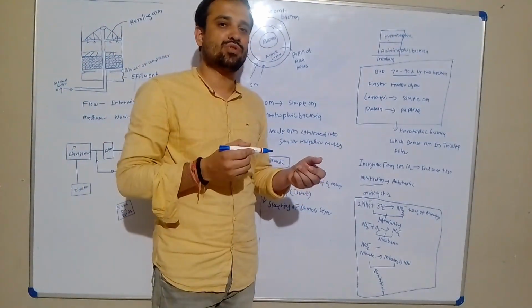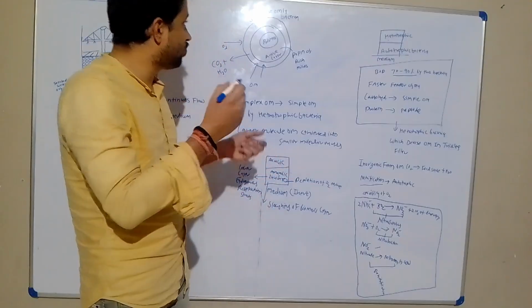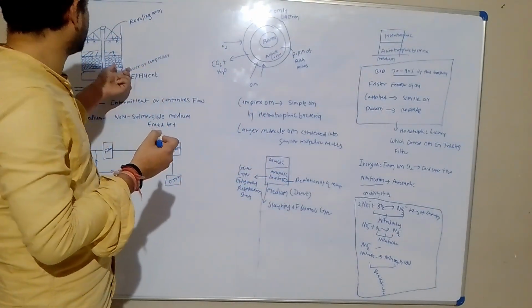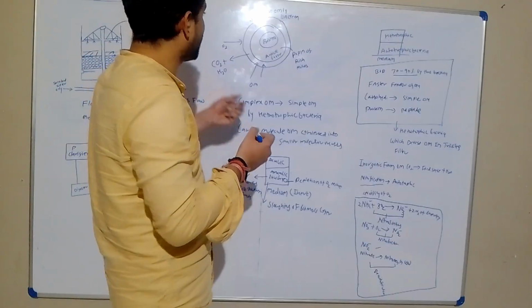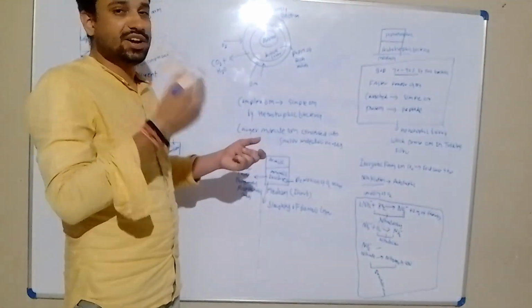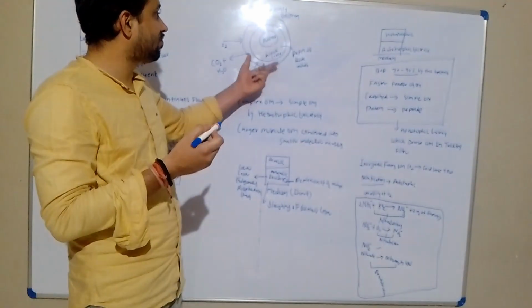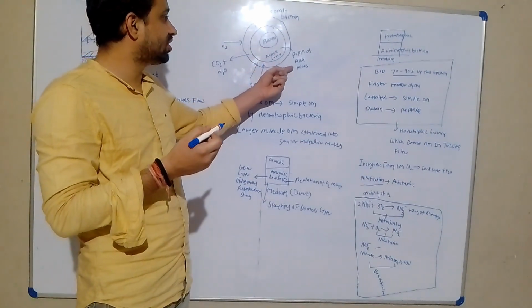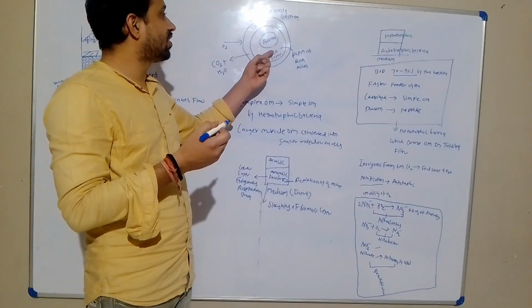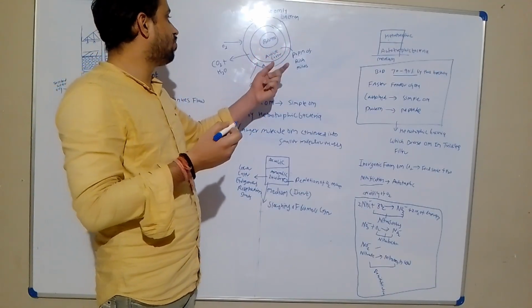The needed O2 is provided for this process by the vents, the blower or the air compressor provided to the filter media. The O2 needed is sufficiently provided for the biomass layer to do the decomposition, and for the microbes present in the active layer, the availability of O2 is more.